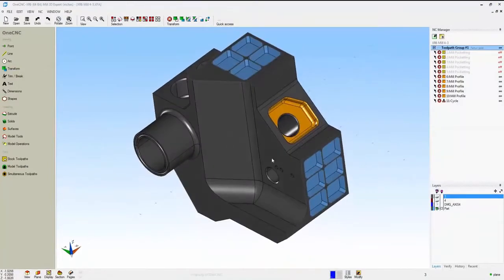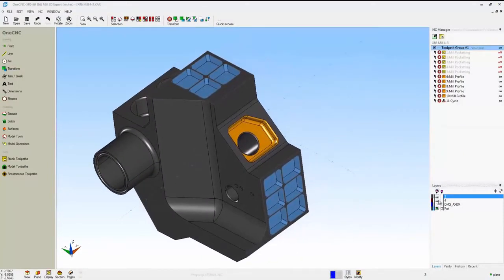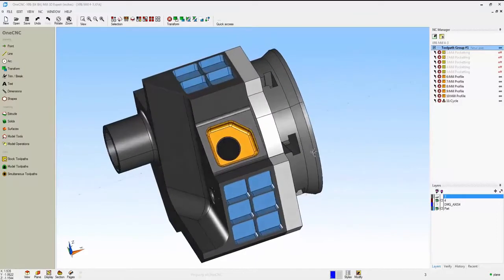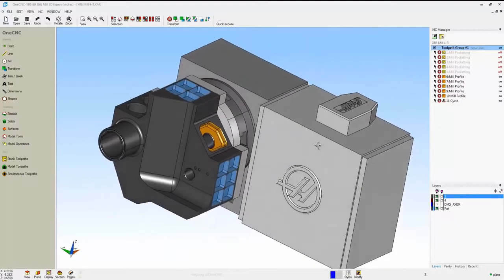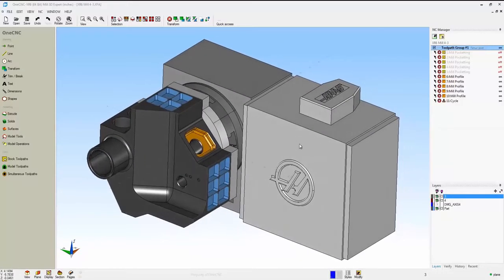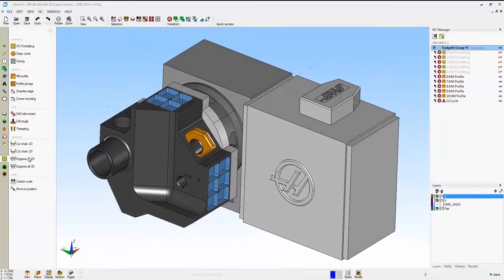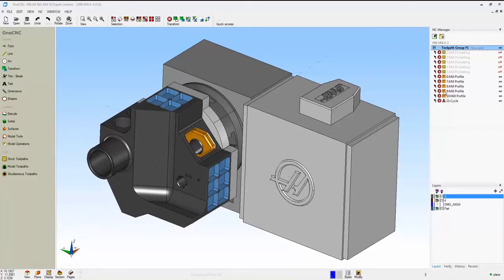This is simply where you index to a side, machine that side, index to another side, machine that side, and so on. Now setting up your fixturing is very simple. Everything that rotates around the 4th axis is on layer 4. Every piece of tooling that's stationary you put on layer 3. You can apply 2.5-axis toolpath to the sides or 3-axis toolpath to those sides as well.